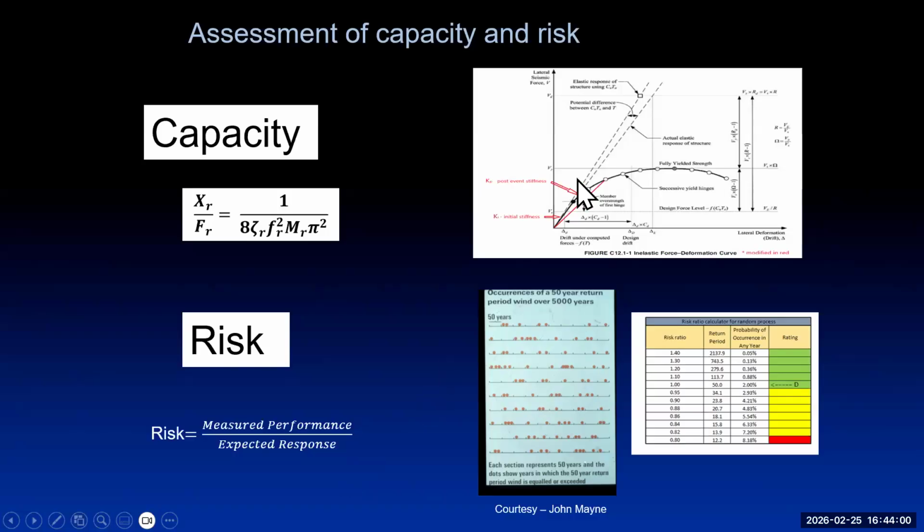Now, on the top right, there's a diagram which earthquake engineers use a lot, and it's a stress-strain diagram. In the linear elastic range, stress-strain is a constant, and then you have ductility. And when you've had a structure which is exposed to a bit of ductility, the stress-strain curve changes. So if you are measuring displacement per unit force, you find a change. All you have to do is look at it before and after an earthquake or a very strong wind, and you'll find a bit of rotation of that characteristic.